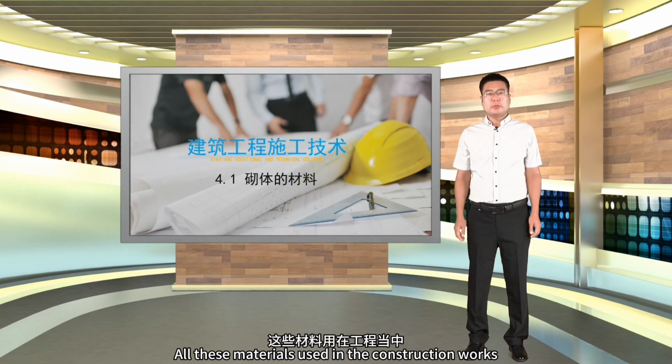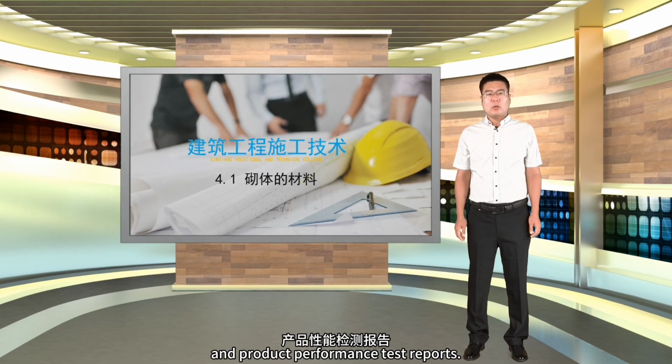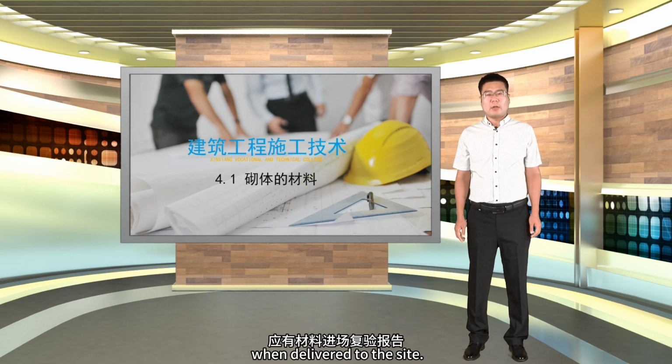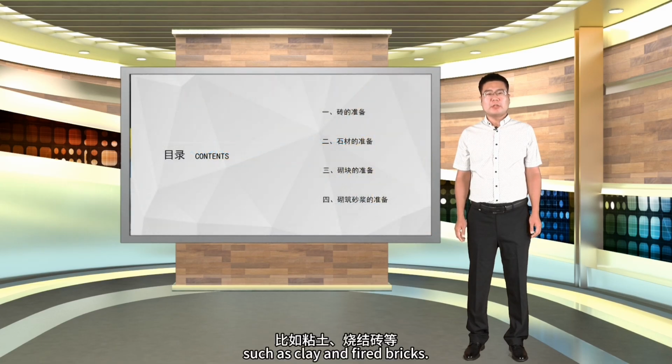All these materials used in the construction works shall be accompanied by product qualification certificates and product performance test reports. Blocks, cement, rebar, sand, and admixtures must also have re-inspection reports when delivered to the site. It is strictly prohibited to use materials banned by national regulations, such as clay and fired bricks.